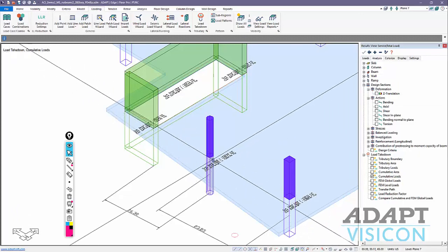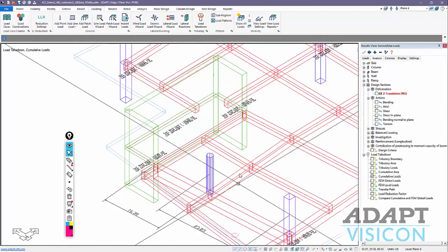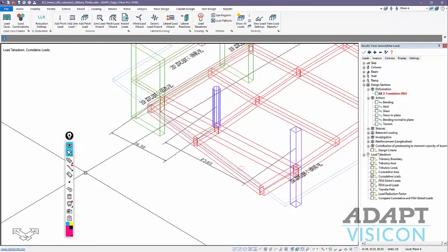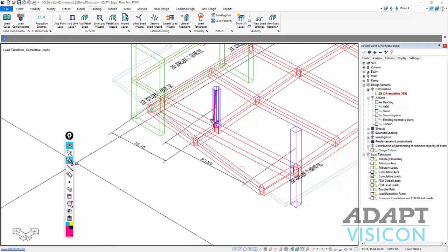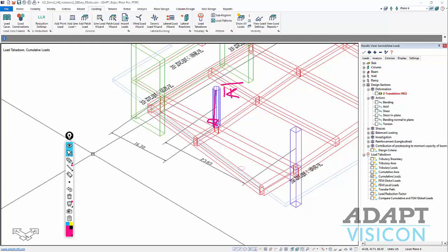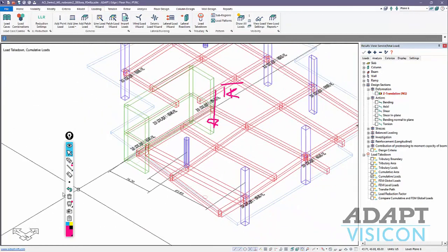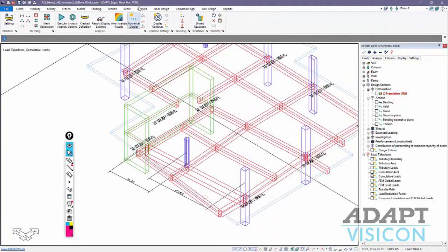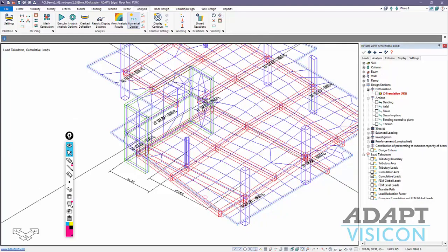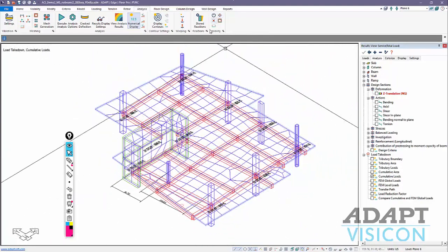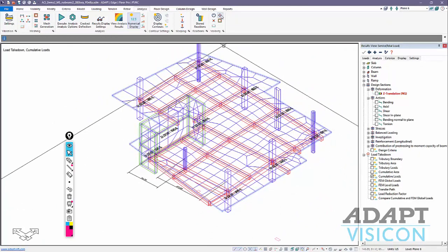So we're now going to design this beam again at this level, but we're going to essentially apply this reaction at the beam. In order to apply this tributary reaction, I'll call it TR, at this beam, I have to rerun the analysis. So I'm in single level mode now, and we're going to go up to analysis. This has already been meshed. If I wanted to redo the mesh, I could, or I could illustrate the mesh here graphically using these visibility tools. But this is already meshed.